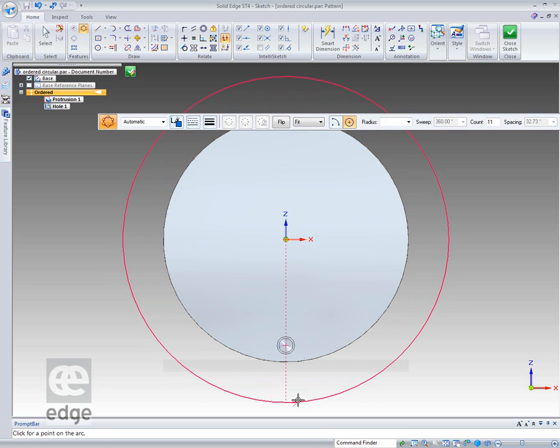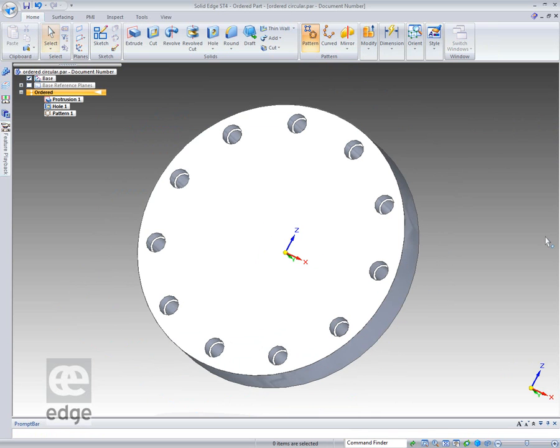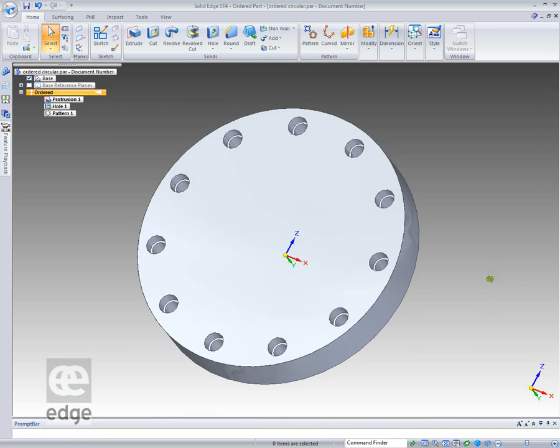I'm just going to pull that straight down, and you'll see a little arrow right down the bottom here. So I go that way or that way. Useful if I'm doing a partial circle. So I'll go to the right. Doesn't really make any difference. And I've got a count of 11 set up in here. And if we go around, we'll count 11 dots. Close it. And finish. And it's done precisely what we asked it to do.